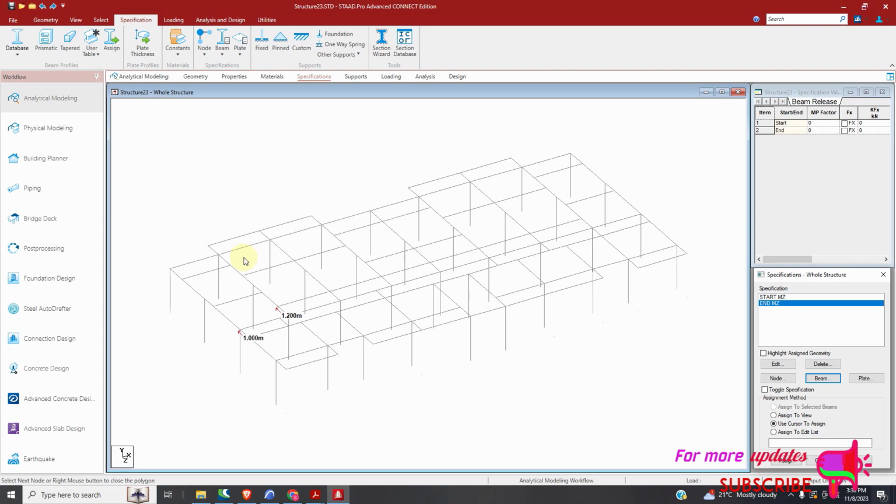So you have to release moment. Otherwise, it will make that point have significant implication during design, and you may find that all those beams, primary beams, will fail because you are now saying that they are restrained in the longitudinal direction. So it will mean that you have to add more depth, to have a bigger cross-sectional area, or even more reinforcement, which is not correct.